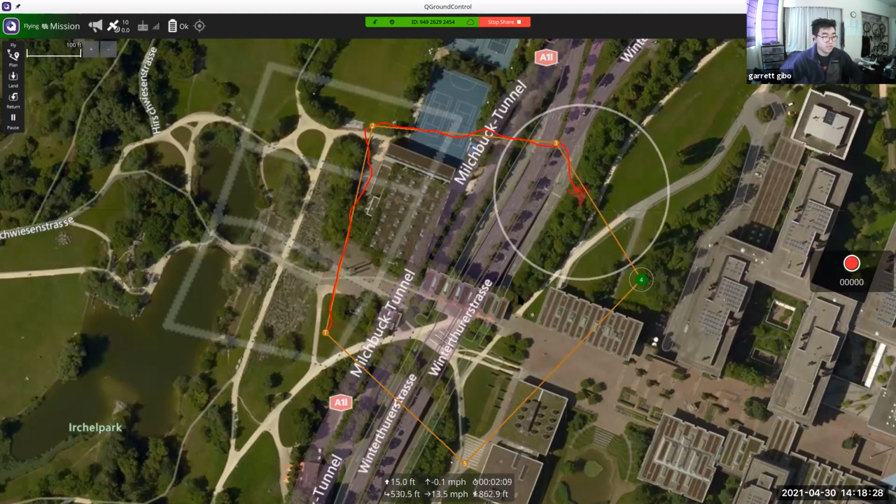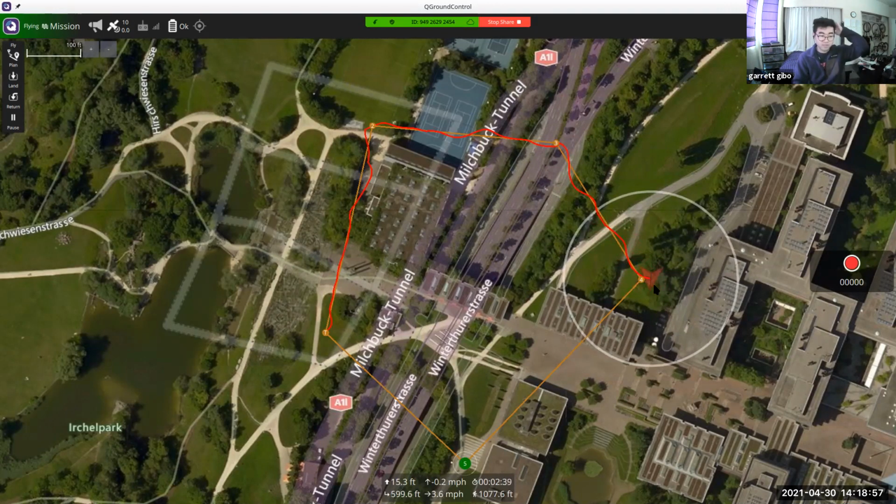The actual model we have of the lander is fundamentally different than quadcopters and fixed wing planes that are used with PX4 traditionally. So part of the main challenge for us is how we adapt the PX4 guidance algorithms to work with this lander. We've handled a bunch of that. At this point, what's necessary is to handle the controls of the vehicle, which translate the instructions inside PX4 telling it to go towards waypoint 2 along some path, and actually send the commands to the actuators of the vehicle.